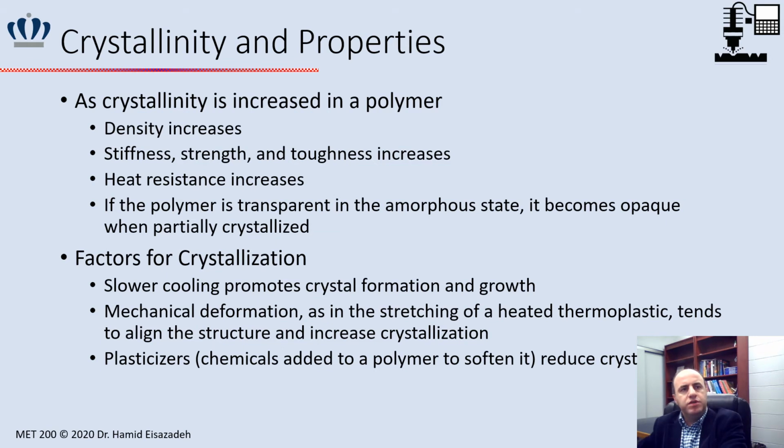In polymers, if the crystallinity is increased, then the density is going to increase as well. The stiffness, strength, and toughness also increase. Heat resistance again increases. If the polymer is transparent in amorphous state, then it becomes opaque when it is crystallized.